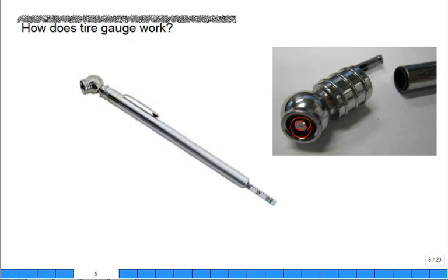And there's typically a little indentation right here to then let the pressure go back through a little hole into the system. But it's supposed to seal on that rubber going around. And if you don't put it on flat onto your valve, it'll leak a little bit. You got to get it to seal. Otherwise, it'll be leaking.